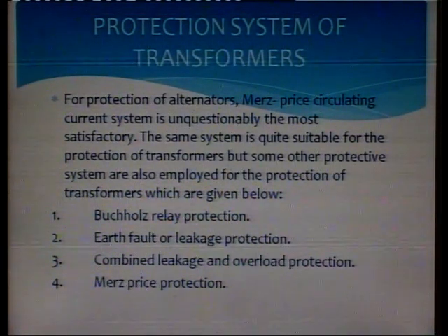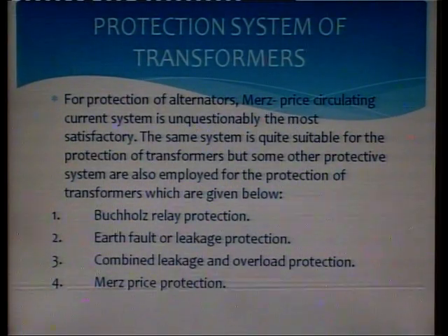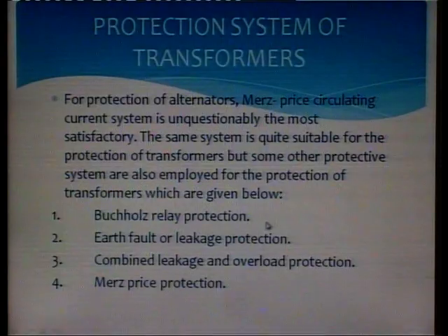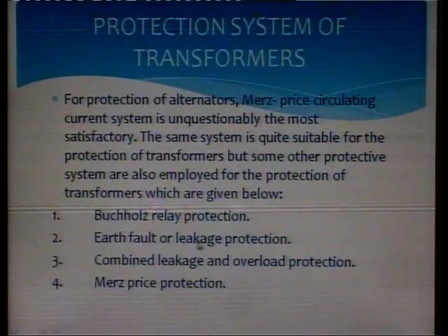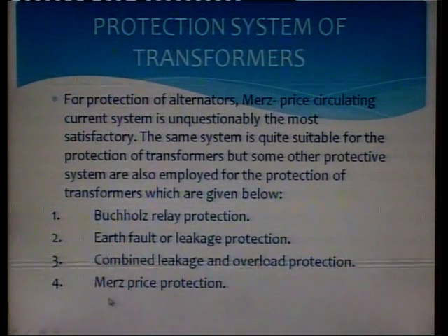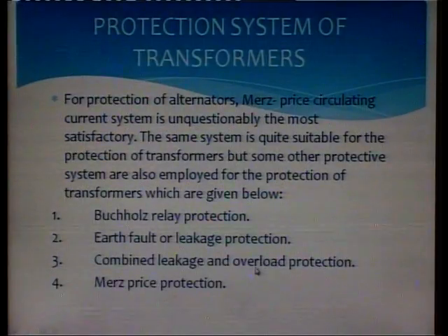First is Buchholz relay protection, second is earth fault or leakage protection, and third is combined leakage and overload protection. Buchholz relay protection is mainly used for internal faults. The second, earth fault or leakage protection, is used for earth faults. The third, combined leakage and overload protection, is provided both for earth leakage and phase to phase faults.